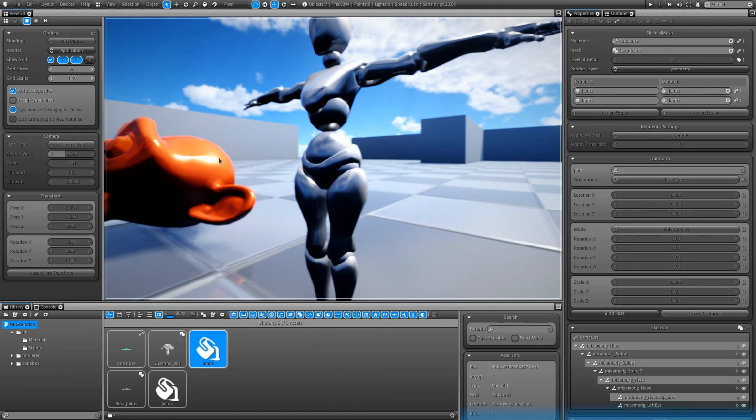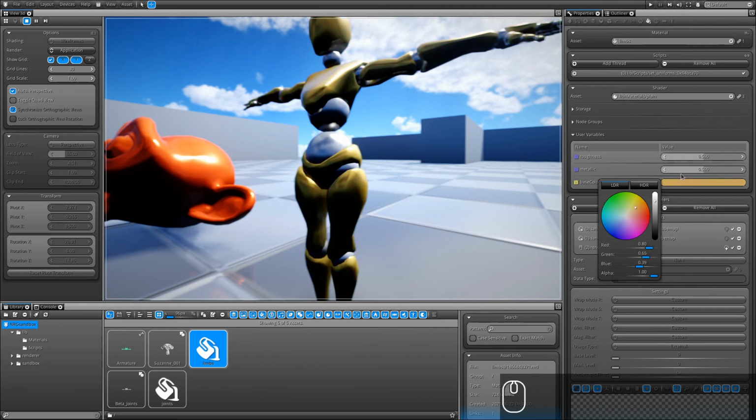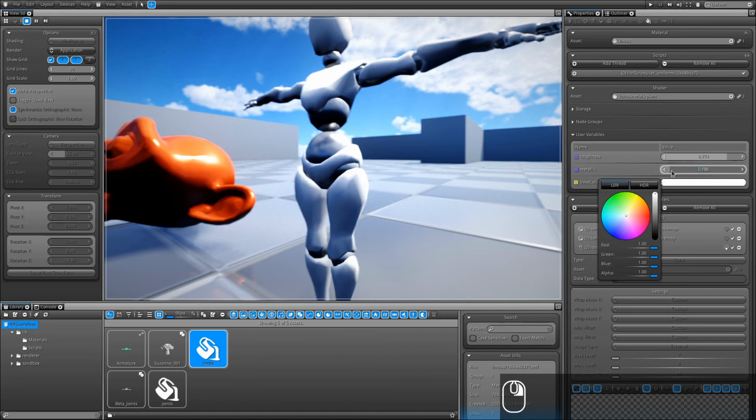We have seen how to change the specific color for a unique object. Now this time we're going to do it on a material level. So I'm going to go under properties and material, and I'm going to click that out, and I'm going to drag and drop my limb here, and I'm going to change the color, the roughness. Let's put it at fully white. It looks better like that, I think. And let's put it fully white, and we don't want it too shiny and not too reflective as well, something like that. Let's say 0.125, and I always like to round things up, 0.75.